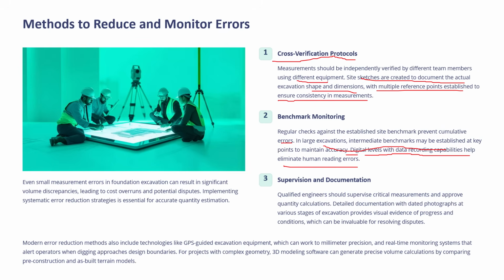And most important is, for all these things you require continuous supervision and documentation. So qualified engineers should be employed who should supervise critical measurement and approve quantity calculations. Detailed documentation with dated photographs at various stages of excavation provides visual evidence of progress and conditions, which can be invaluable for resolving disputes.